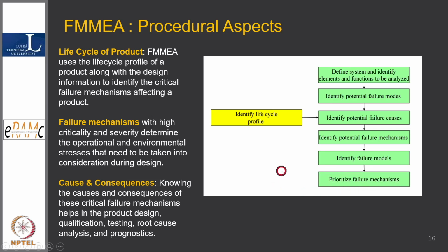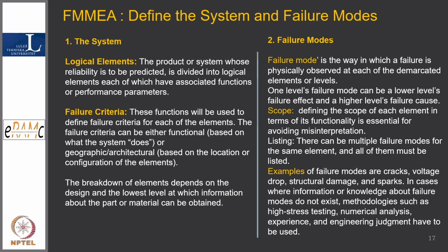There could be more than two to three competing failure mechanisms, and we have to see which one gets the highest priority. It's not that we will ignore other mechanisms, but we will take them into account. Most of our modeling will be on the competing, most important mechanism. There is something called importance analysis in probabilistic analysis, and we have to do that kind of exercise.